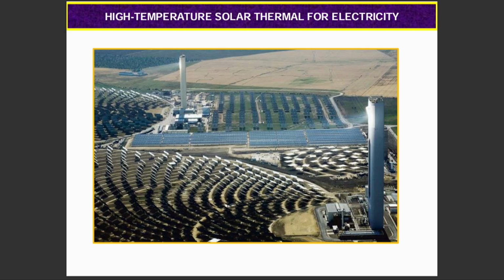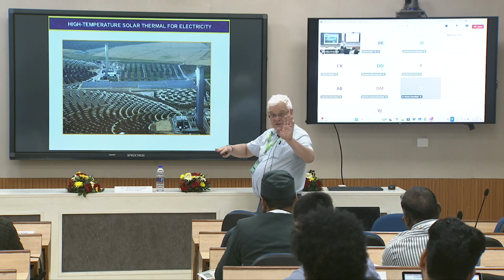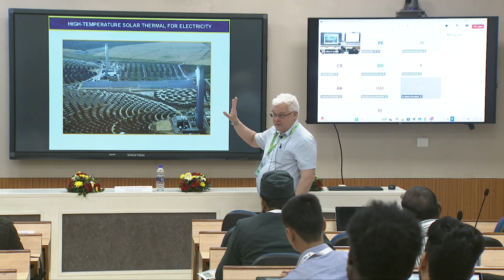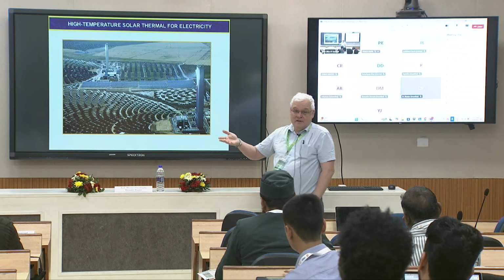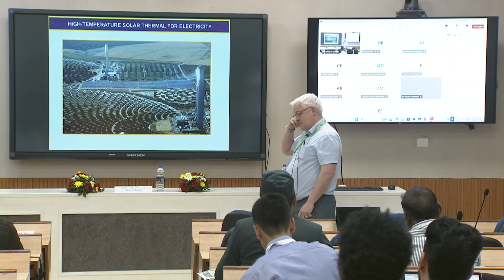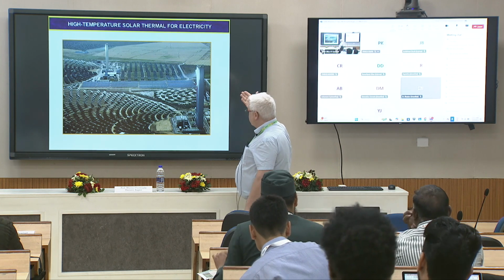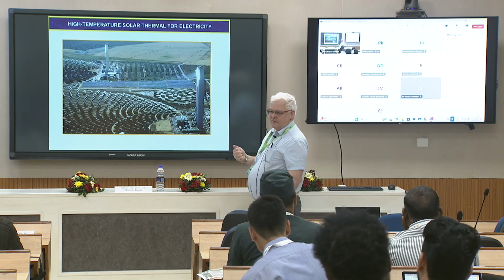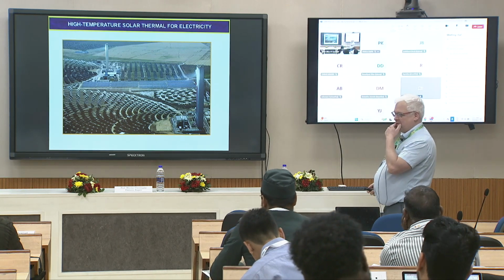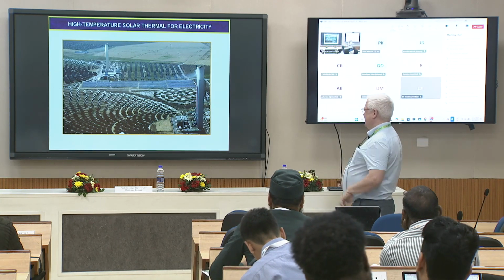So there was an attempt to make hybrid PV concentrated solar using PV panels on the heliostat, because the heliostat in principle is very well oriented. It's a kind of sun tracker finally. So if you put PV on the heliostat, it's good for PV production, and they were expecting to recover part of the concentration, but of course you are losing a lot compared to a mirror. Okay. You need more cooling. Yes.